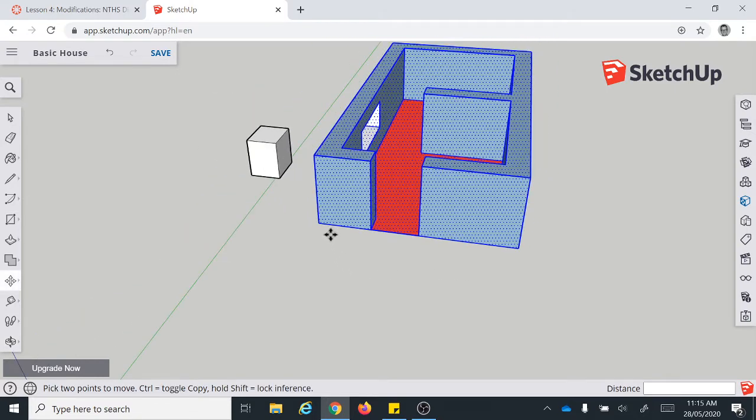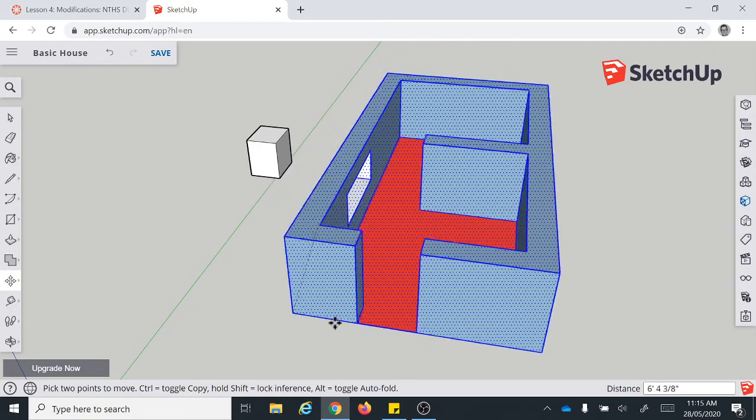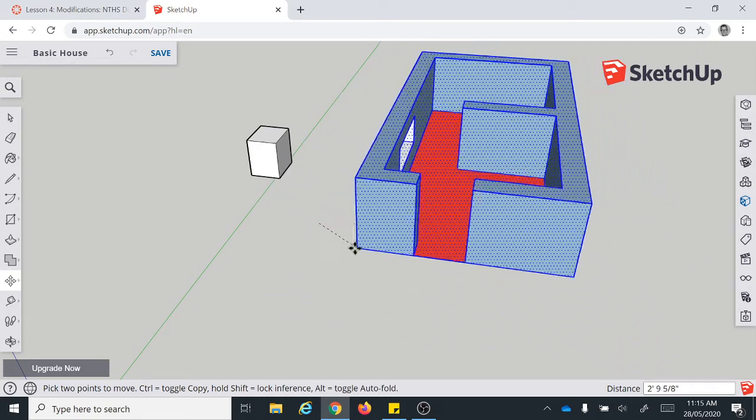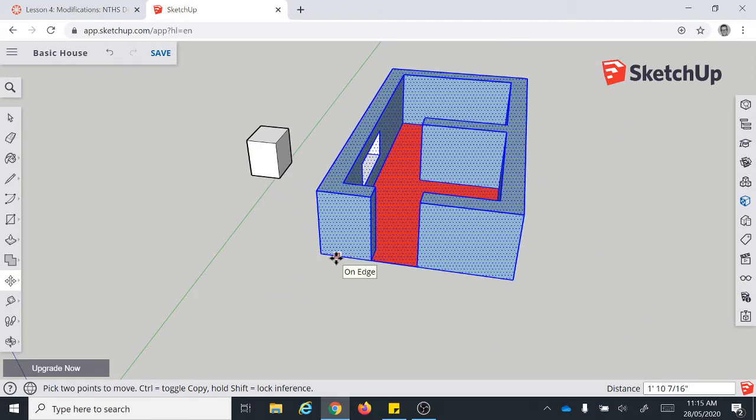You can also be clicking on different endpoints or midpoints, and you can use that as your location that you're going to move around on as well. So the second one is we'll look at the scale. Now you can click down here on scale. The shortcut also is that you can press S on your keyboard once you've got something selected already.